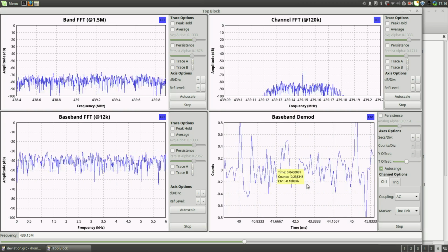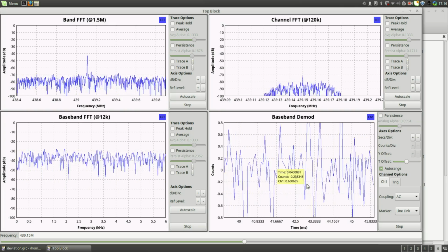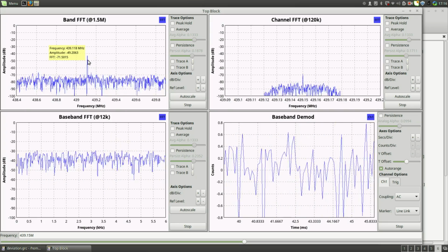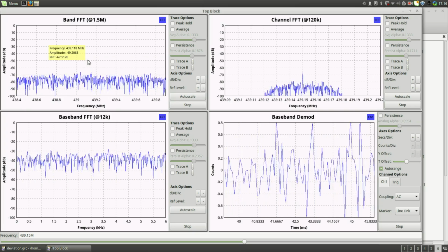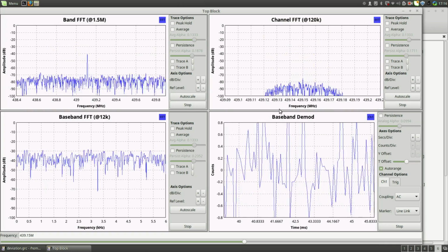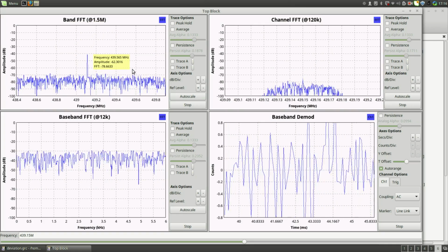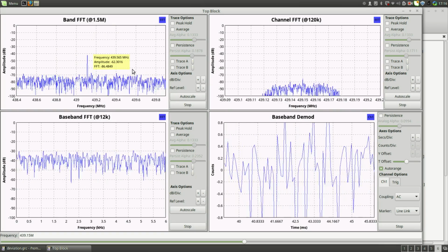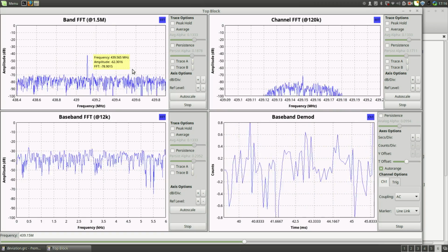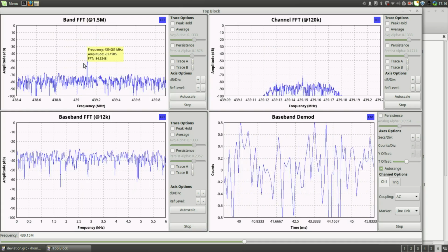Okay, so now let me start transmitting without any modulation, so I get just a carrier. Let me turn it off. Look at this, that's the carrier here. I turn it off, the carrier is gone, and if I turn on the transmitter again, I get this carrier here. Now interestingly, I don't have a carrier here, and the reason for that is even though my SDR hardware is tuned to 439.15 megahertz, the crystal clock reference inside the hardware is fairly poor. Actually, it is so poor that I have a frequency offset here that I don't see here.